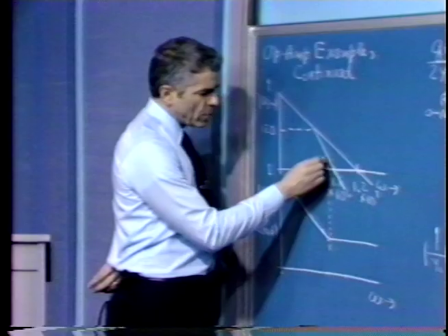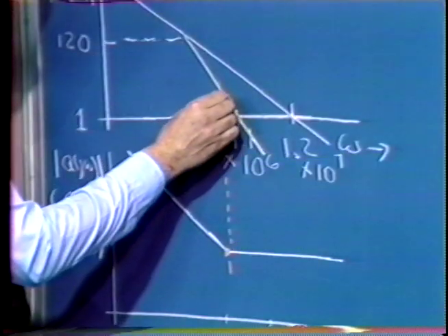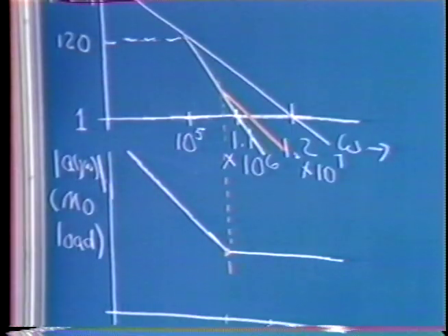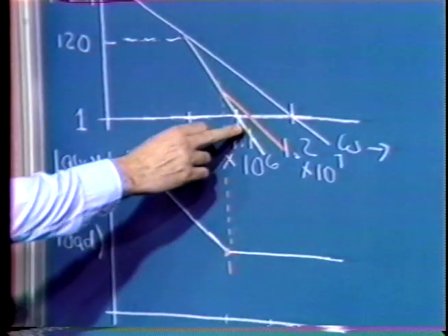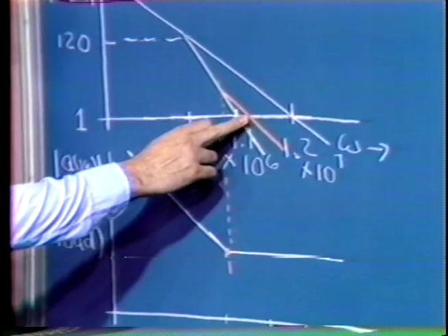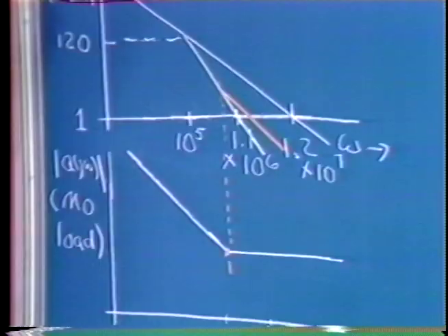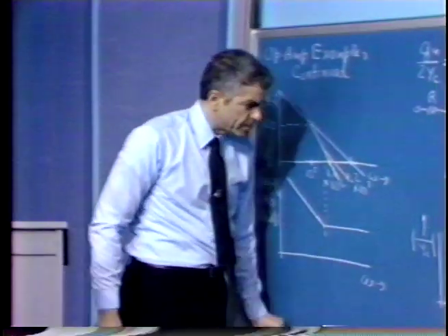As a result, our overall loop transmission, or the negative of the loop transmission, might look something like that. The hope is that, of course, we greatly improve the phase margin by virtue of having added this zero to the loop transmission. Let's see how that works.